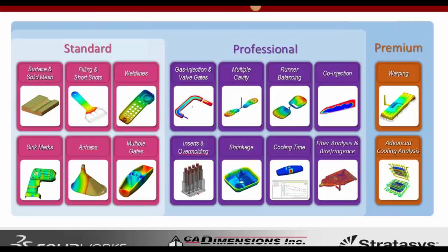So just to go over what we did here today, we used SolidWorks Plastics as a solution. It allowed us to obviously fill the part. We were able to use the analysis results to look at our shrinkage, give us an idea of how much to scale that model up. Initially, I said 1%. As I looked at the model, maybe it was closer to 2%. And also, we were able to use warping analysis to predict the warp, and then create an anti-warp.